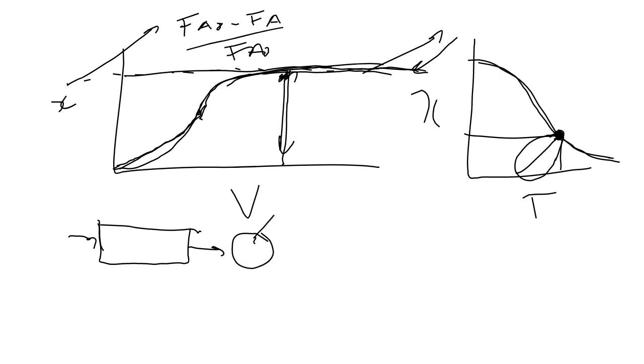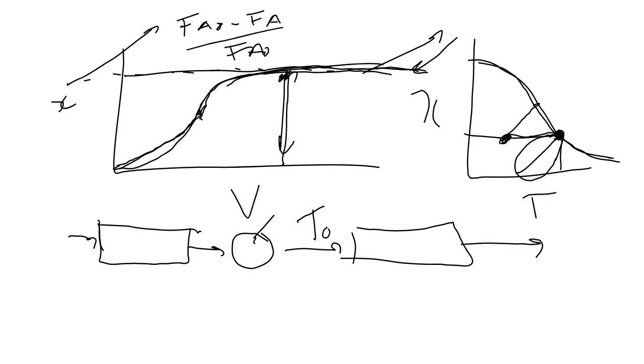Then of course, if I cool it down at equilibrium, I can start again with the next PFR reactor, because now I've changed the inlet temperature, so I can specify a new inlet temperature there. But the question that I asked in terms of minimizing the volumes doesn't exist anymore, because you can't operate at a maximum rate. For the second reactor, you will see the same kind of behavior. You will have an X and it will go until you achieve equilibrium.